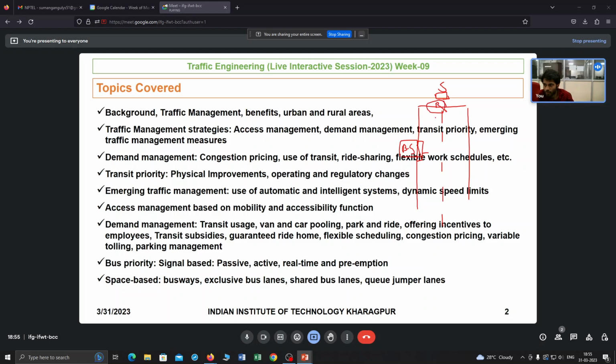So generally what happens is the buses are here only. So now buses not only wait at the red signal, but also they will only clear this signal after these queued vehicles clear, right? So not only signal delay, but also the congestion or queuing delay of vehicles.